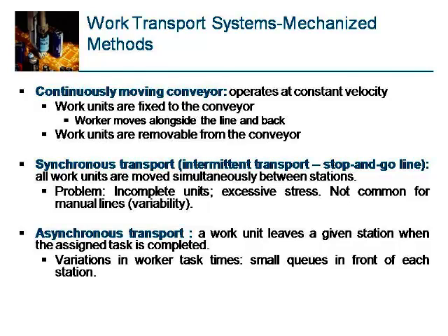The previous work pieces will be moved to the next workstation for the operations. So there the transportation is intermediate transportation, a stop and go kind of line. Belt conveyors, roller conveyors, moving finger type conveyors or several other mechanisms for this kind of operation are in use.